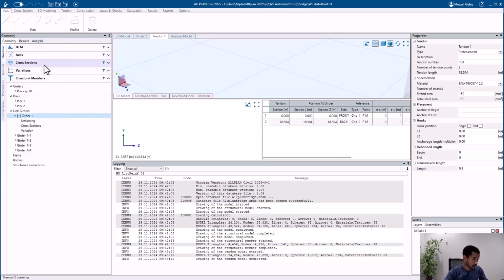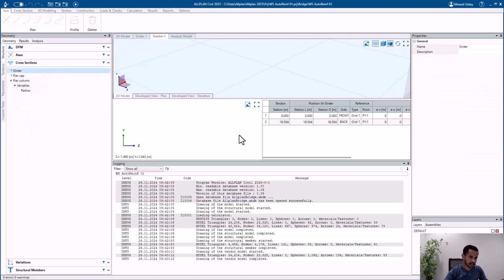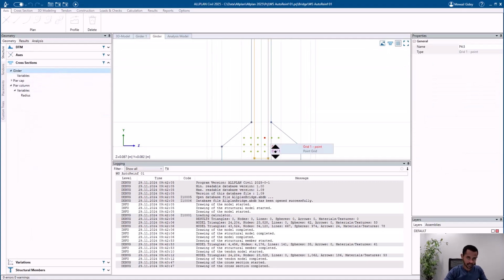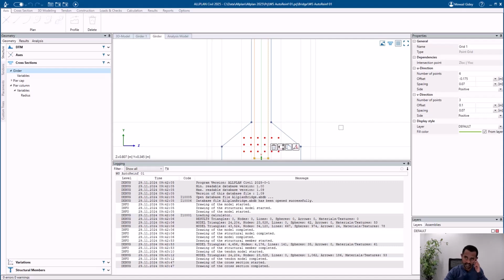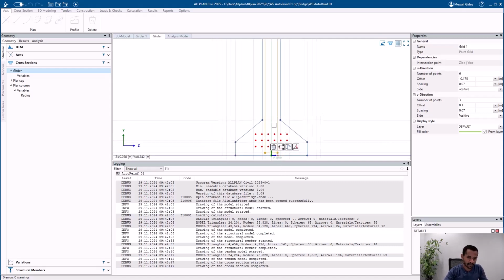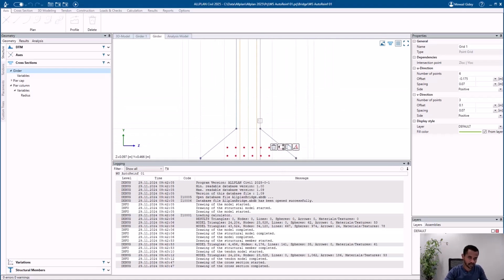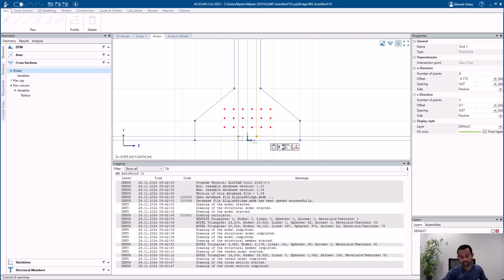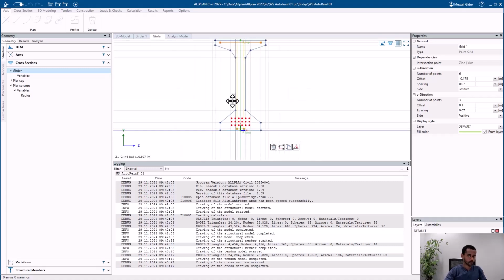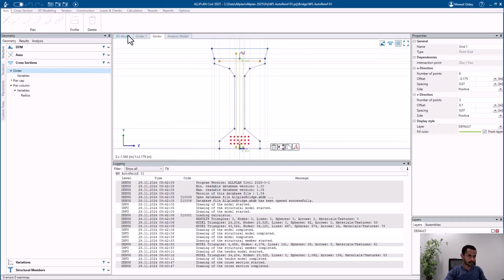And tendons are normally created directly in the girder. Here we could create them using grid lines, as you can see, and we would basically have all the definitions that we want for the cross section here, and we can say, okay, I want to have the transversal bars there, so you could really avoid also the tendons, and you could create the reinforcement definitions as close as to what it would be on the construction site. So this seems the end of this example.